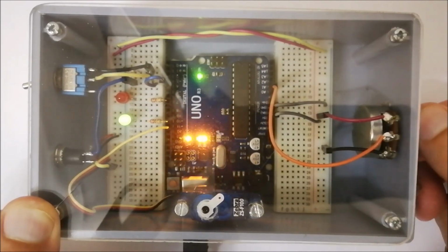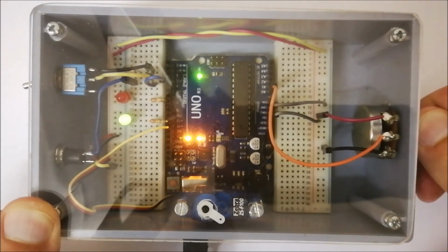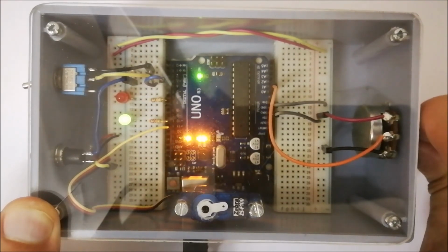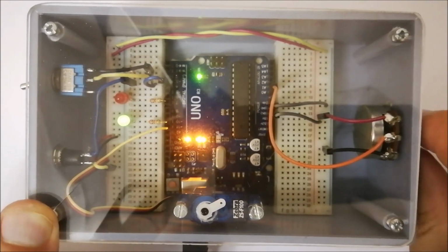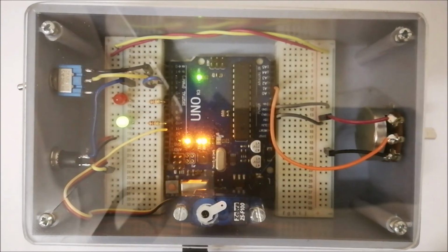And so we're able to now control the actual position of it using the PWM. It's to do with how many degrees and the position of it, whereas in the previous case we had to look at the flashing of the LEDs. Keep in mind you do get servo motors that are full rotational, and with the PWM output, it could give you a full rotation.